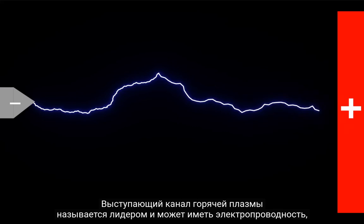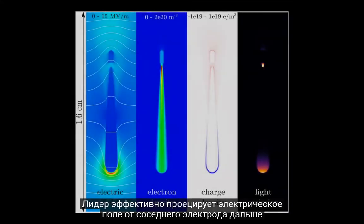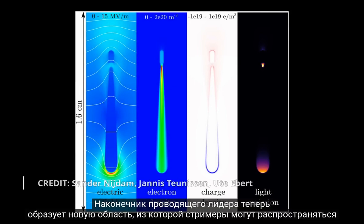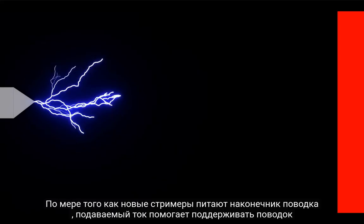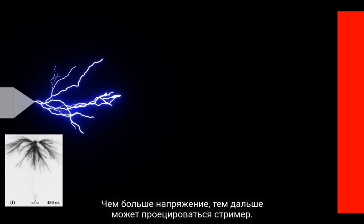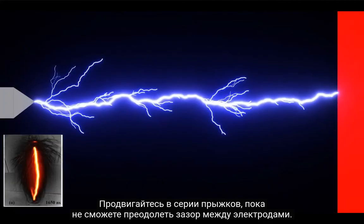The projected channel of the hot plasma is called a leader, and it can have an electrical conductivity approaching that of an electric arc. The leader effectively projects the electric field from the nearby electrode further into the gap. The tip of the conductive leader now forms a new region from which streamers can extend even further into the space between the electrodes. As new streamers feed the tip of the leader, the current supplied helps keep the leaders hot and conductive. The larger the voltage, the further the streamer is able to project, progressing in a series of jumps until it is able to bridge the gap between the electrodes.